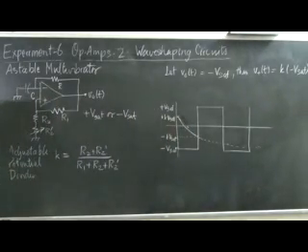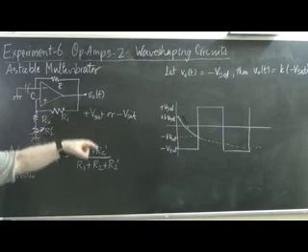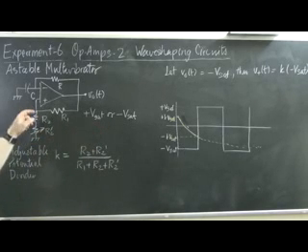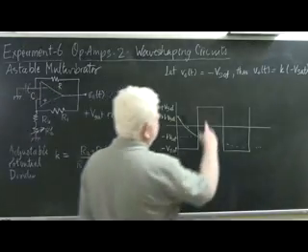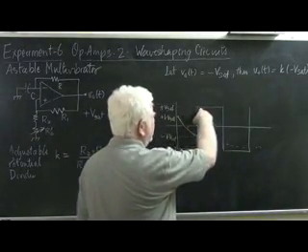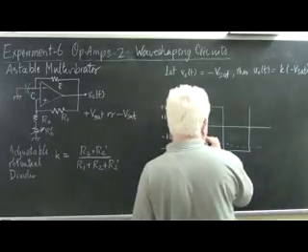that is present. So as the capacitor voltage falls downwards towards minus Vsat but achieves a value of minus k Vsat, the inverting terminal voltage falls below the non-inverting terminal voltage. And as soon as that happens, the op amp will switch to plus Vsat, as has happened over here. As soon as the output of the op amp switches to plus Vsat, the capacitor turns around from its current value of minus k Vsat and starts charging towards Vsat like this.